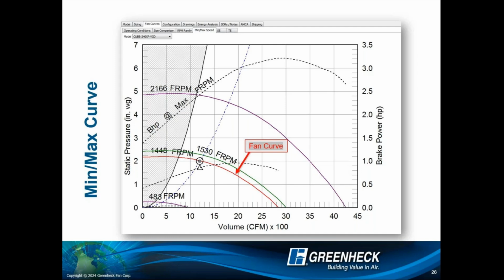That's right, actually, and an excellent point. And then on top of that too, just staying away. You'd like to be in a good spot there. You might need more distance from the motor system limit, but staying away from that surge curve is always a good idea. But then you are playing with fan efficiency, which we'll get to in a little bit.